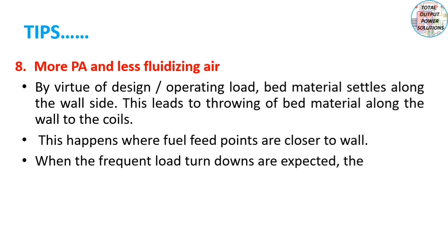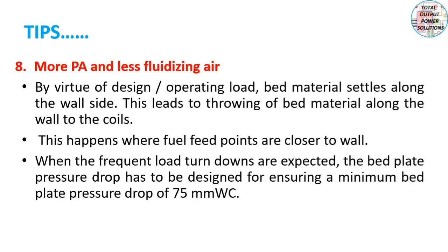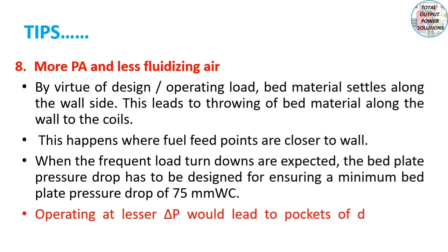When frequent load turndowns are expected, the bed plate pressure drop has to be designed to ensure a minimum bed plate pressure drop of 75 mm of water column. Operating at a lesser delta P would lead to pockets of dead zones.